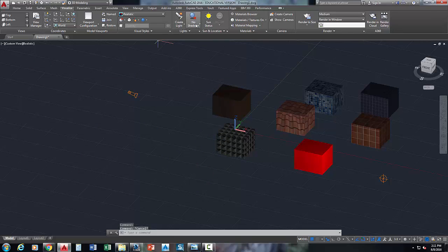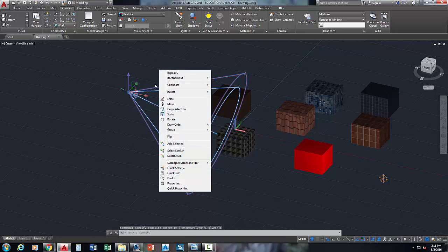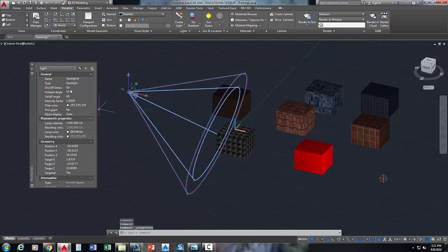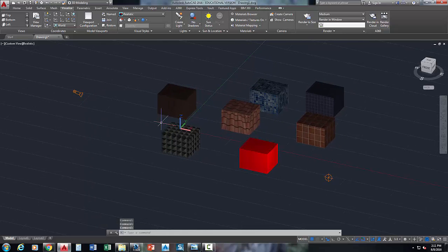I don't know. You've got this down here that says no shadows, but the shadows they're talking about are ground shadows, not shadows from one object to another object. So it's already set to no shadows, but you can still cast a shadow from one object to another. I haven't figured out, since they took that away, how to make that light. It used to be right here where you just could turn off shadows. So maybe it does already. Maybe in 2016 they don't cast shadows anymore. I don't know. So that's lighting.